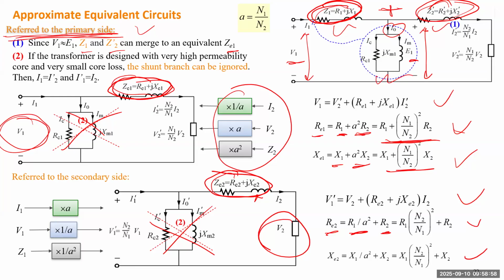So if you define a base value, for instance, for the primary side you define 220 kV as the base value, any voltage will be divided by the base value. You will get the percentage of operation. Similarly, for the secondary winding, you have maybe 35 kV. You also use that as the base value. The percentage will be the same. Okay, so that will be addressed by the per unit system.